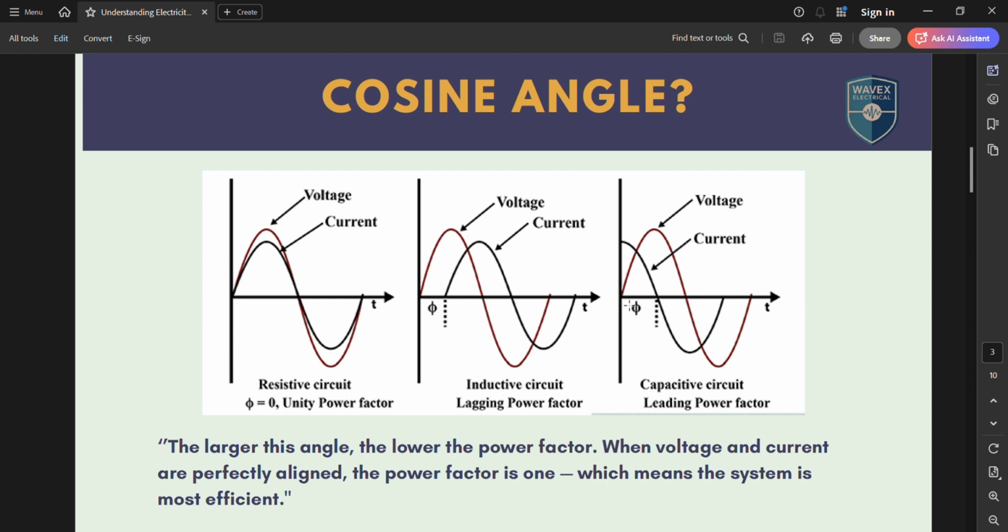Okay, you can see the peak values of the current and the voltage waveforms are different. See, the current waveform is here and the voltage waveform is this one, the red one. The current peak value starts from here itself, and the voltage peak value starts from here. So there is a difference, and that is why this is called leading power factor. Leading power factor is for capacitive loads. The best example is capacitor banks.